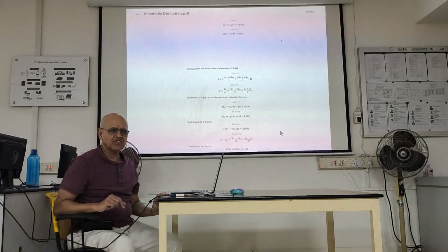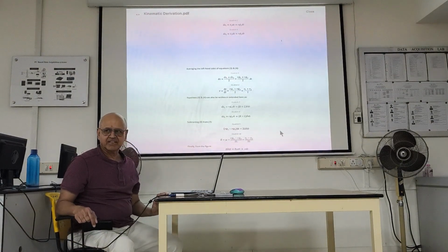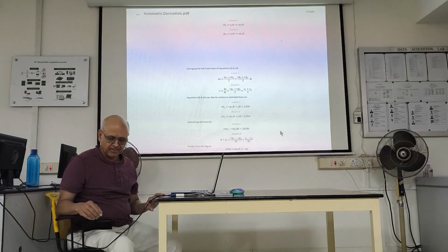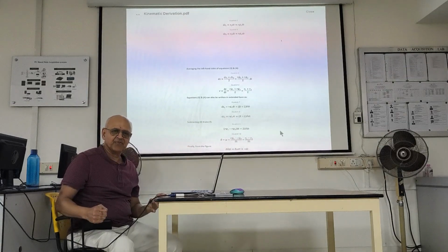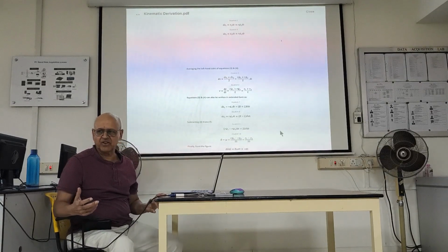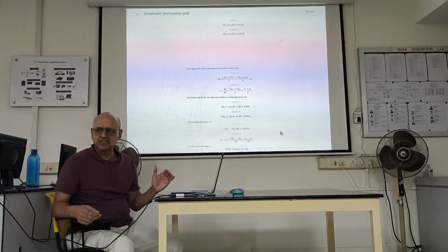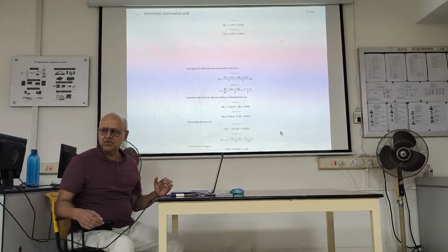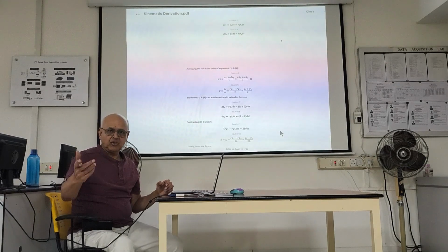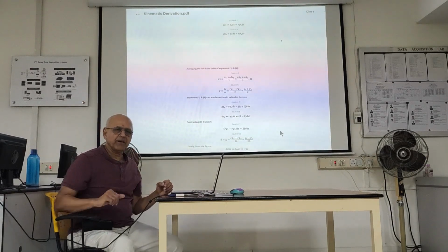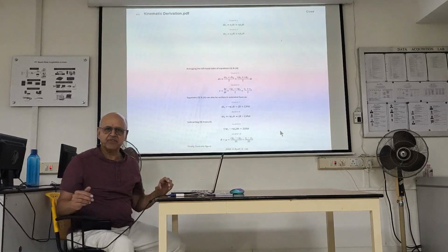So what is the radius of curvature? Just imagine the circle. You're drawing a circle with the right wheel, not moving, because velocity is 0. But the left wheel has a positive velocity. So what is the radius of curvature? You should be able to do it from V by omega.